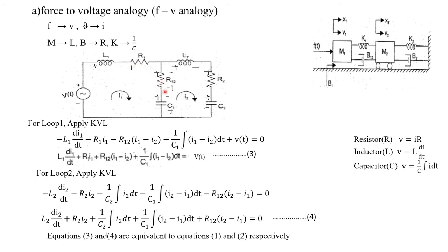In this way, we can represent all the elements of mass M1. Okay, so this will be represented in the first loop. While representing each and every term for the mass M1, the elements which are connected only to this mass M1 will be represented here, as well as here. In these two branches. And the element which is common to M1 as well as M2 will be connected here. So this is the common area to loop 1 as well as loop 2, so here you have to represent the common elements. Understood? So no need to draw any elements here because this is a ground.